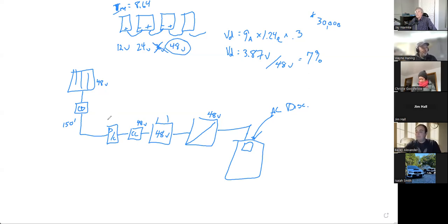And what that means is the charge controller comes in up to 600 volts, and then it does a DC to DC voltage conversion within the charge controller, and it steps down the voltage to 48 nominal. So now we can do our array up to 600 volts. So what does that do to our system?